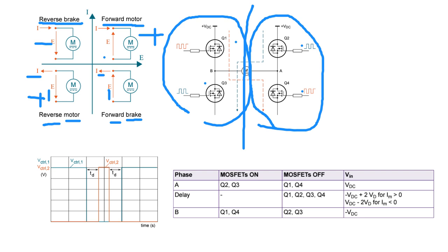Yani you can imagine you have a ventilator in your home. You need to regulate your speed function. Your ventilator works in only a single direction with different speed levels. You can use only one MOSFET. Okay, it will work as a motor. You need to regulate your speed. If you don't want to regulate the speed, for example, you apply 12 volts to your DC motor. It works at full operation at only a single speed level in only one direction.